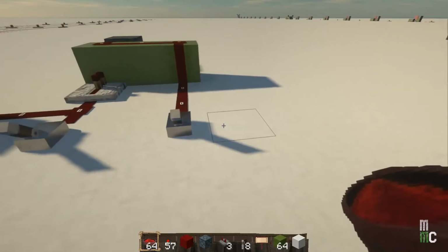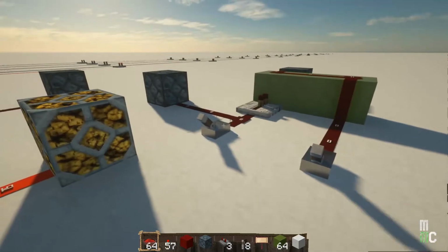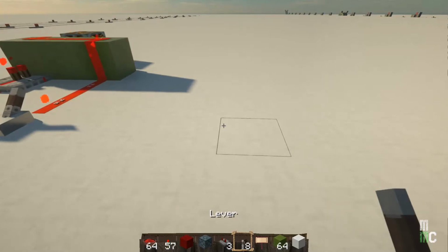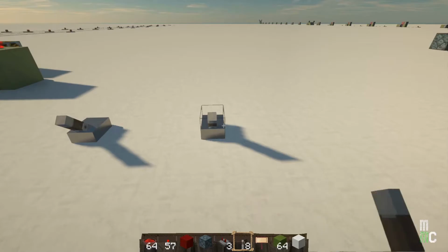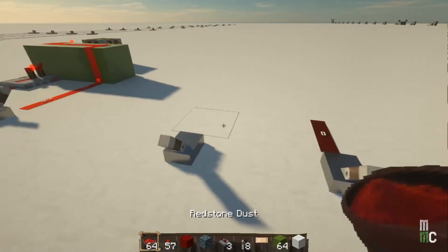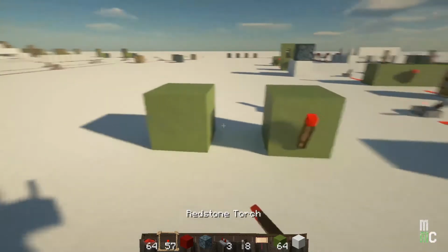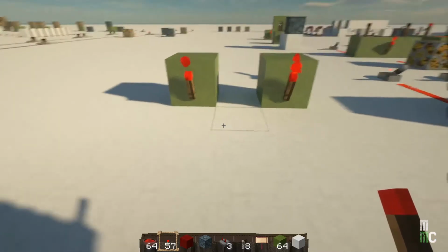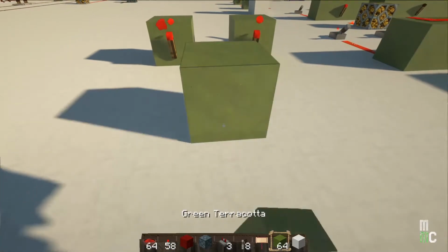We also want a gate called an exclusive OR, where I only want if one or the other. So this would light it, but it would be turned off in that case. So we'll add a couple of switches here. And these will be our inputs. I'll run those. And the way this is created is we need two NOT gates, a NOT here. Those are going to be connected together with wire and run into a third NOT gate right here.